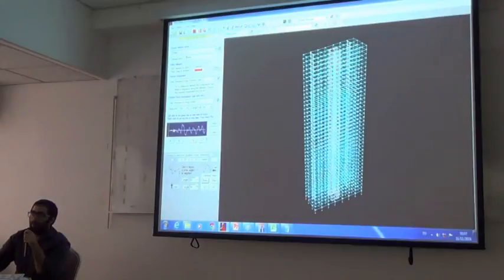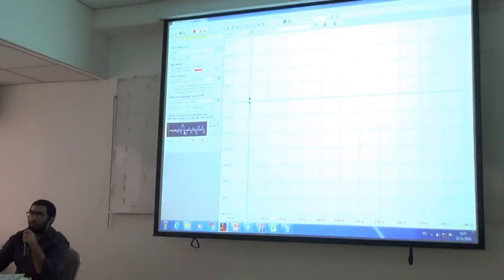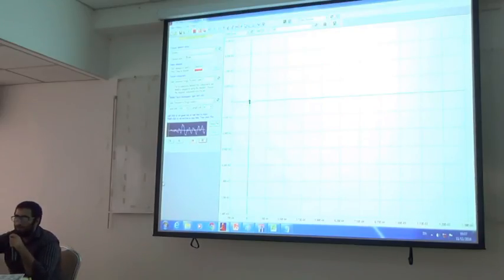So if I am right, let's say the red cursor is here, that means the amount of force at this time step is this much. This much is the moment in the girder at this time step. If I continue plotting it, you will see that the force is increasing. With every time step, the force continues to change, and there will be a time step where it has already yielded, and then time steps where you will get some higher rotation demand. Right? So something like that.